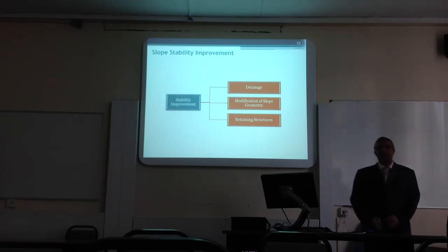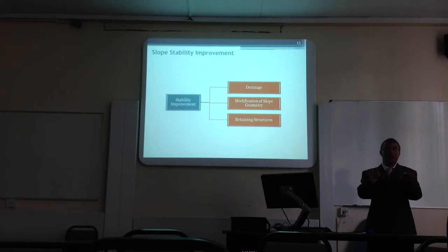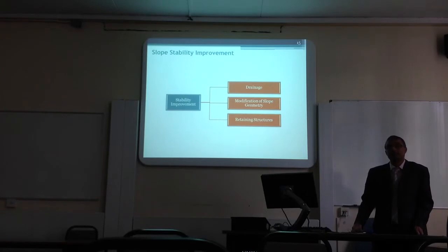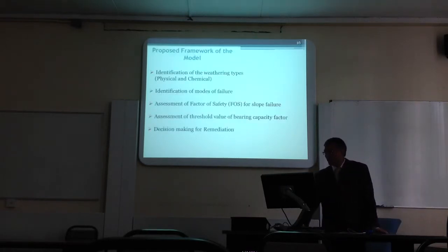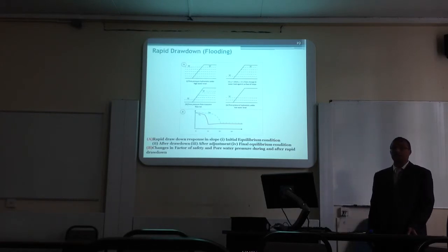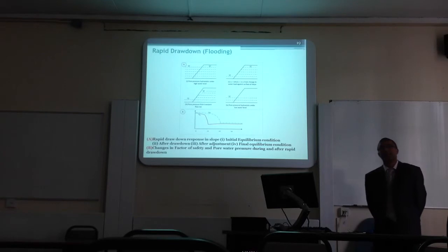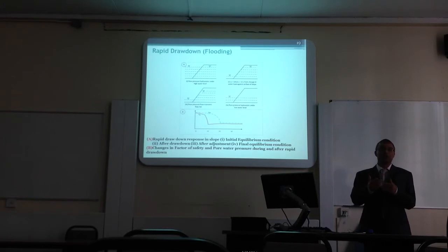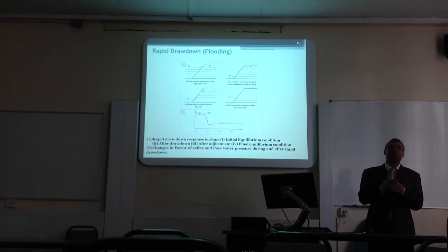So you've got an embankment, and it's flooded. What's happening to the water? The water will be there until... I'm trying to understand, because you've done flooding as a rapid drawdown. To me, there'll be situations which are rapid rise. You're just focused on rapid drawdown. But if you've got an embankment and there's a flood event, the water level tends to rise and it floods the embankment, which is the opposite. Yeah, but we are trying to say the failure occurs due to rapid drawdown.